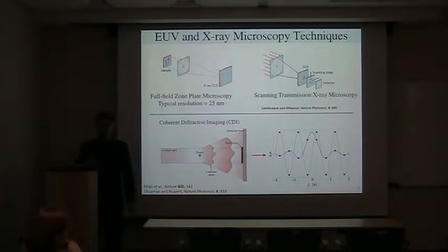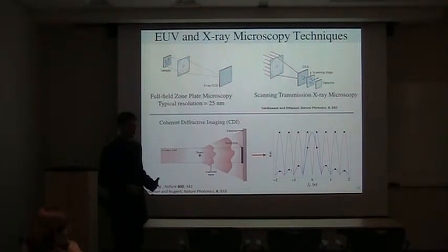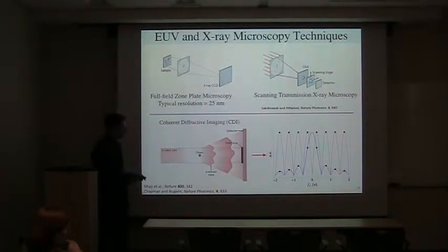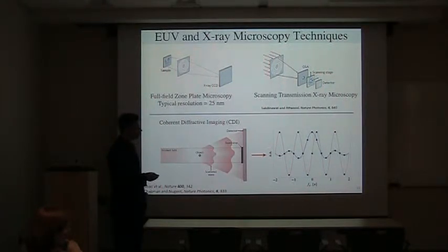But it turns out that we actually don't measure the amplitude. We measure the intensity. This is a nonlinear operation that essentially doubles the frequency of the signal. Okay, so now this signal is not sampled properly, so it cannot be reconstructed from its samples. But if we Nyquist sample the intensity, we look back at what that does to the amplitude. Now the amplitude is oversampled.